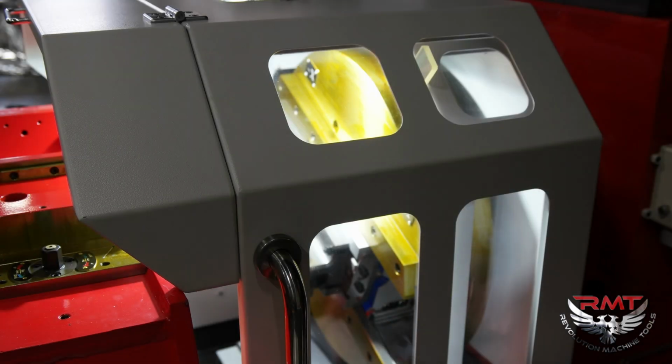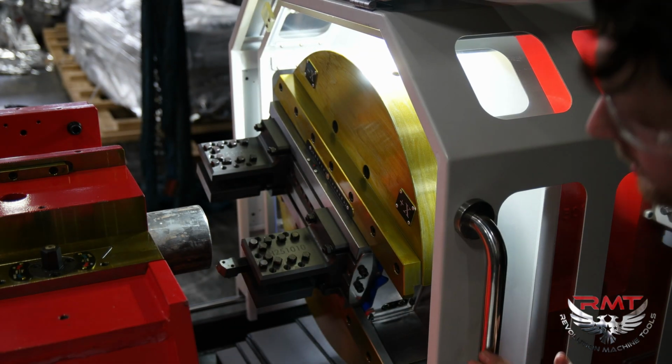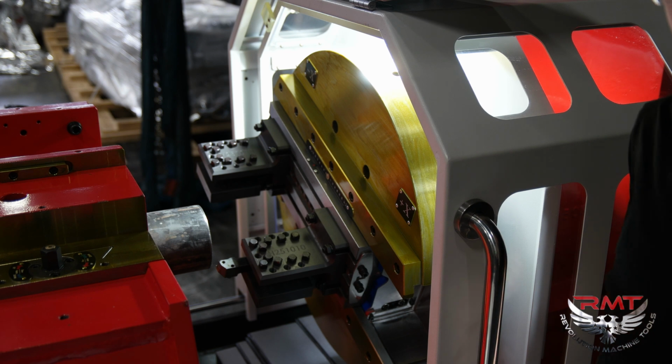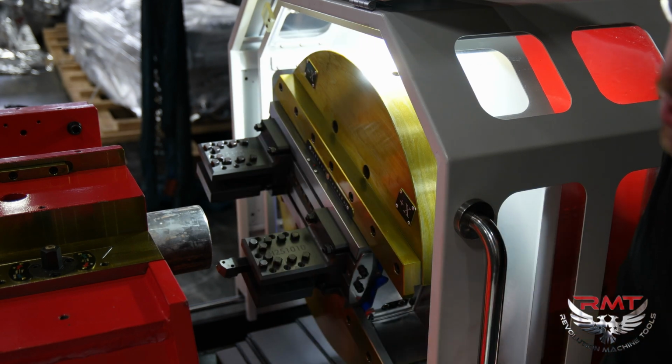All right, so now my spindle's off. I'm going to open up my cover, and then I would go over to my controller and type in the necessary information to touch off for the X of that tool. Now, I'm going to treat this as my tool 1, and with my tool 1, I'm going to set my G54, so that's what I'm going to do next.